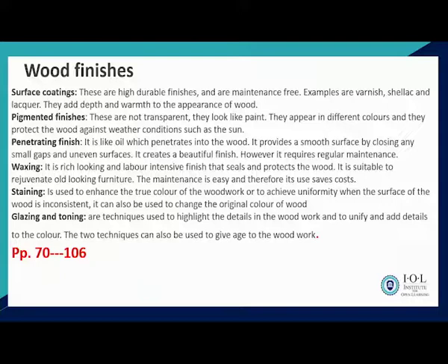Then we've got pigmented finishes. These are not transparent. They look like paint, and also they can be bought in different colors, and they protect the wood against weather conditions such as the sun. Then we've got penetrating finish. It is like oil which penetrates into the wood. It provides a smooth surface by closing any small gaps and uneven surfaces. It creates a beautiful finish. However, it requires regular maintenance.